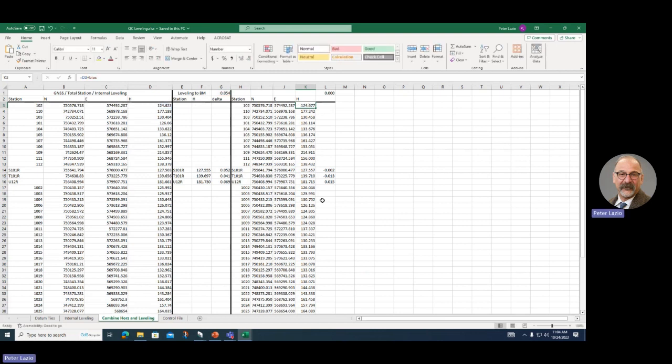Once I do that shift, my differences are 2,000s, 13,000s, 15,000s, and you can't level that well over those distances. So I did not care about my error factor for my leveling because I know it was not going to change my values. I didn't bother taking the time to redo it.